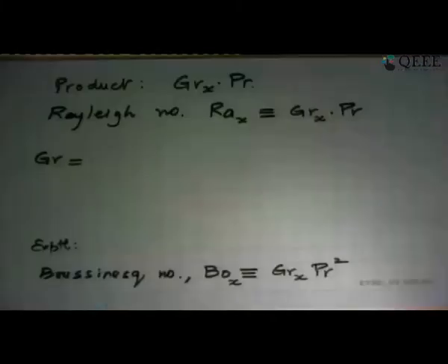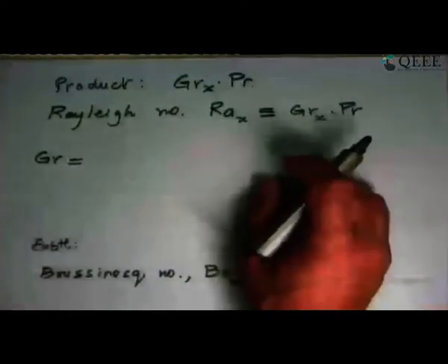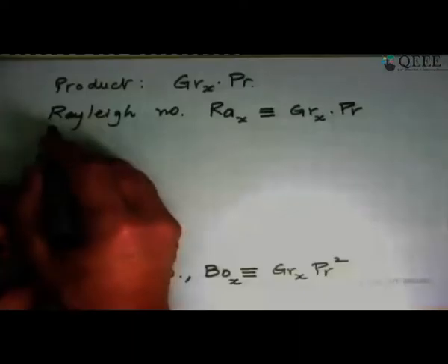Okay, so with that, we got that non-dimensional equation worked out, and we'll define a few more slightly modified terms over here now. The product of Grashof number and Prandtl number appears quite frequently in many correlations, it also tells you what is the dependence of Nusselt number on Prandtl number.